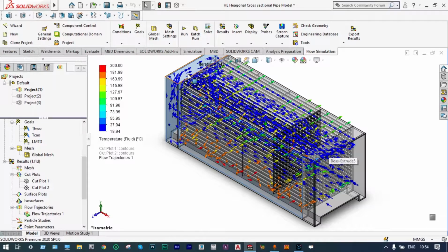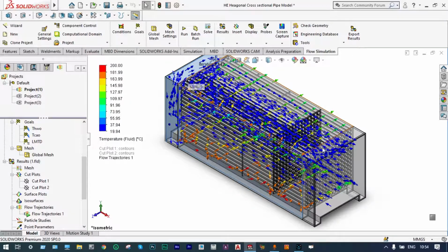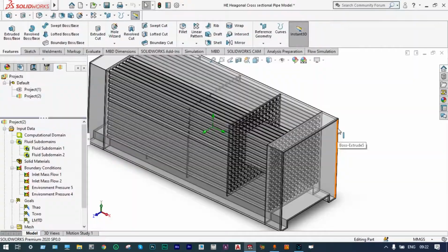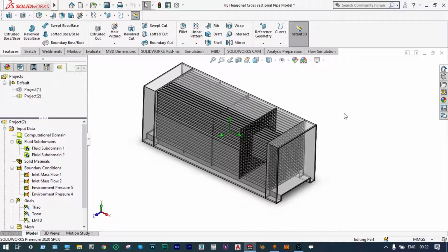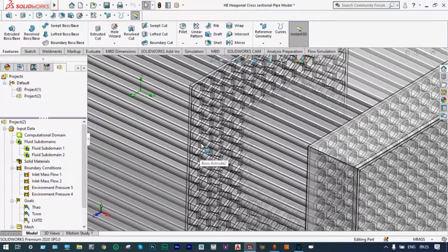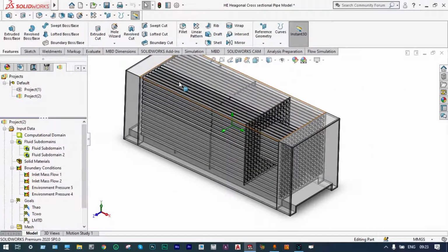The modeling part has already been made. So here in this case we'll go for only analysis, parametric study and optimization. So let us import the model. This is the model. For understanding the dynamics of flow particles, we have made the model transparent. You can see here the profile cross section. It is hexagonal tubes, and in between we have provided 3 baffles, and this is the exit location and this is the inlet location, and this is the side walls.